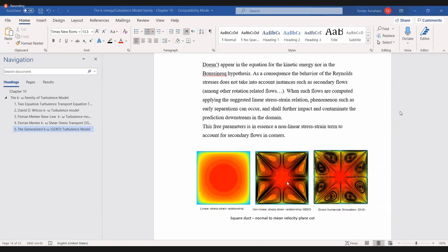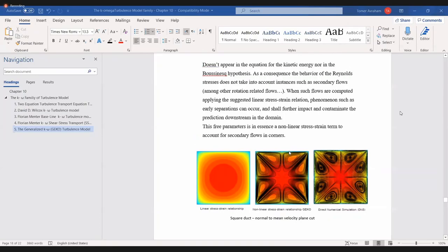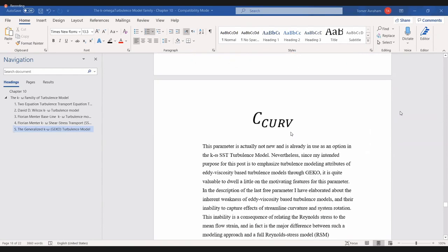Or you can also use the explicit algebraic Reynolds stress model, because it's a lot less stiff than the RSM. Okay, so you can use it if you think you have recirculation areas. There is another way to capture recirculation areas, which is the Jones-Launder correction. Do not use that. It usually makes problems everywhere you have stagnation areas. So be very careful using it.